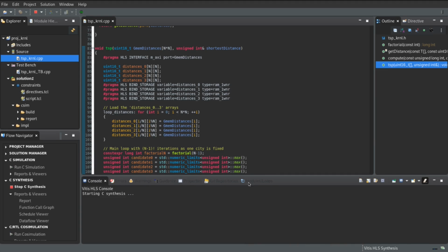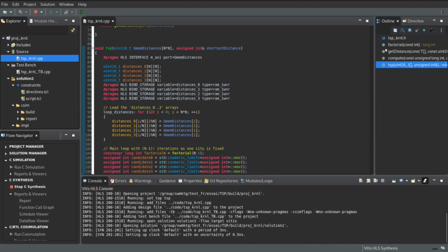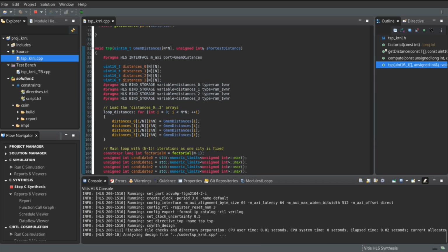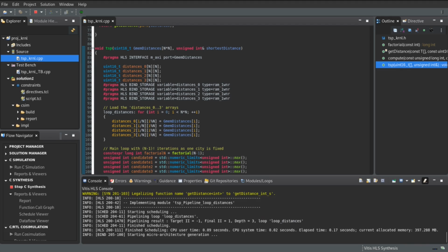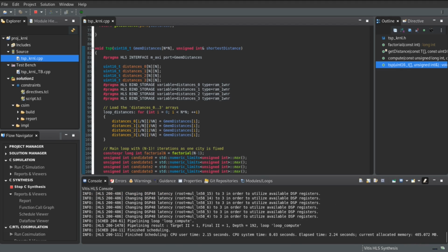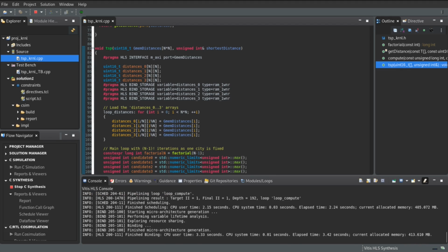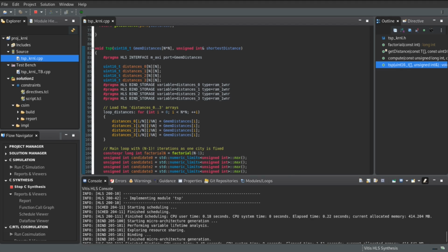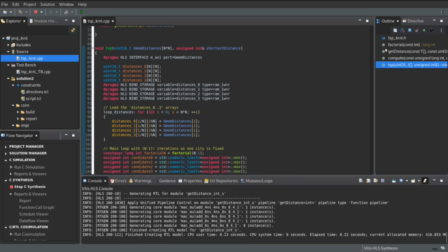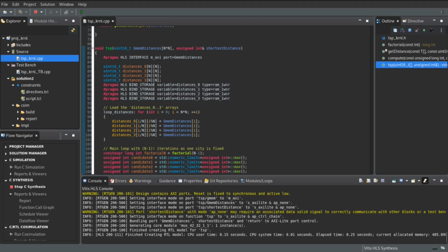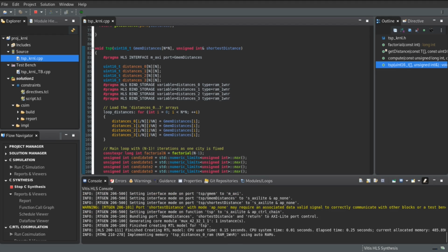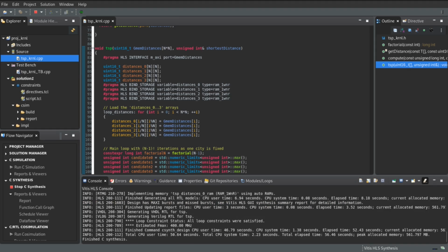Let me start running the C synthesis for this kernel. It only involves the kernel and takes longer than a simple C compilation, since it will need to implement a microarchitecture based on the user directives that are supplied. It will schedule the necessary operations and associate them with a library of operators and memories in the binding phase. And based on this, it will generate the RTL files that represent the behavior in a hardware design language with a choice between Verilog or VHDL.